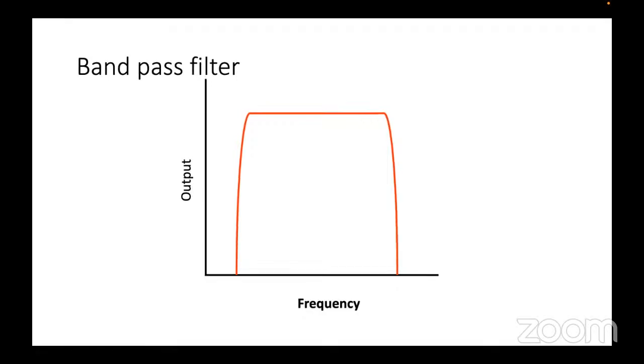And these are used when you look at the ECG. When you go into the filter mode, you'll find there is a monitoring mode, a therapeutic mode, and a filter mode. So you can select that and get rid of those frequencies which are interfering with your monitoring. You can see that the diathermy filter lets you get rid of the disturbances from the inductance from the diathermy. So band pass filters are an important part of it.